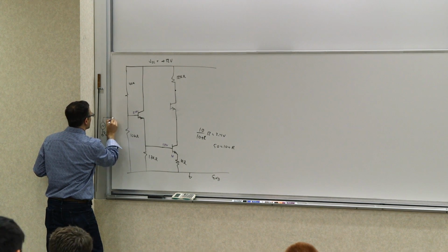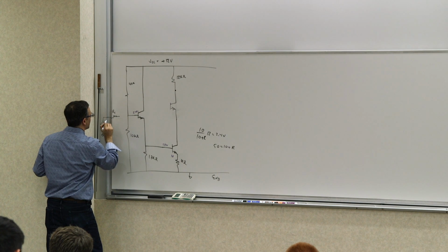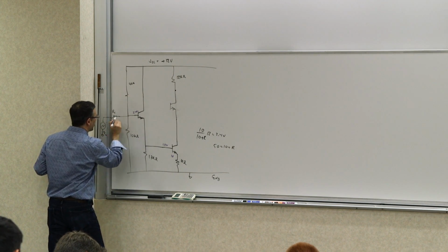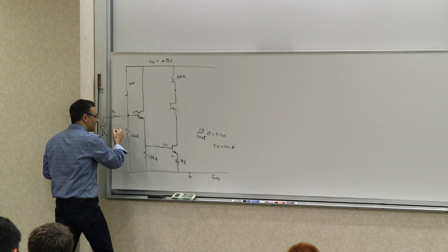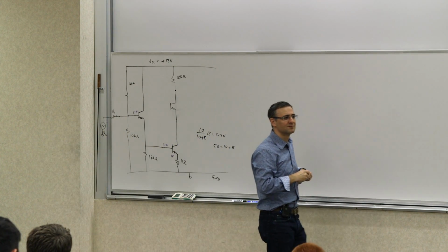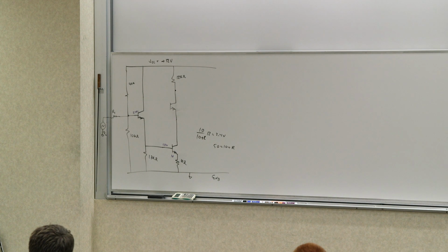And then I have a source resistance, R1. Can I just connect this here like that? What happens if I do that? If I just take this and connect it like that, we short circuit that source to that input. The input will get overridden by the supply.